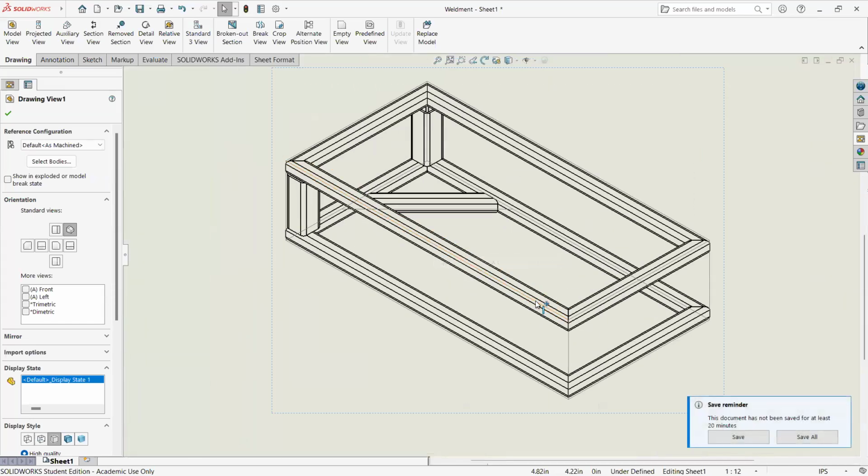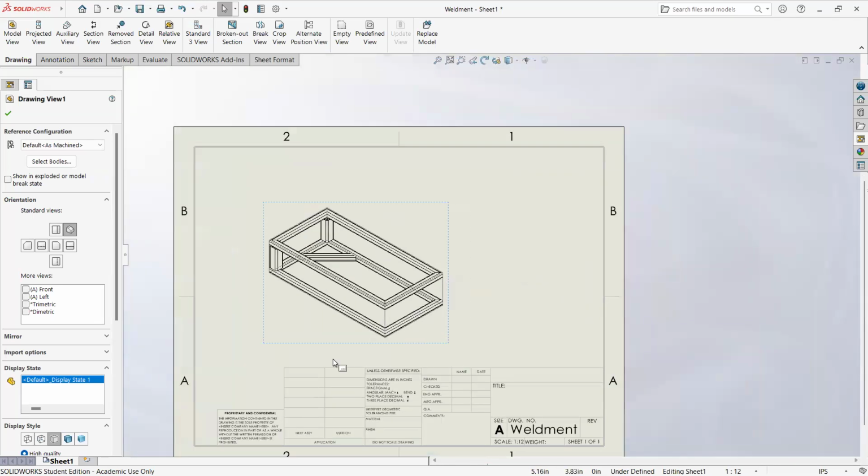Create different parts for the different lengths with mitered corners. But that can be a nightmare as we have all of those files to update to make a change. Like you saw in the video how quick it was for me to change the entire look of how this thing goes together, the alignment of the profile, all that good stuff is a bit of a nightmare if we did these as separate parts. This way, it's much easier to make changes without having to change anything.